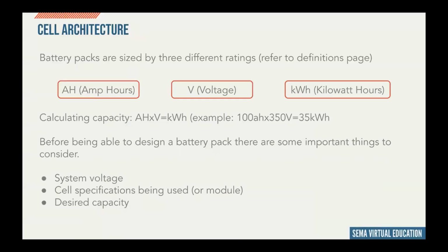So, getting into cell architecture and the way that battery packs are sized. This is some very important math for step one of designing a battery pack, which is taking three very specific ratings, which are amp hours, cell voltage, and watt hours, or in higher capacities, kilowatt hours, and calculating the overall specifications of a battery pack.